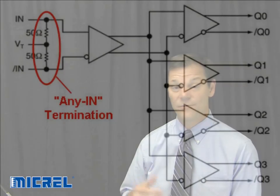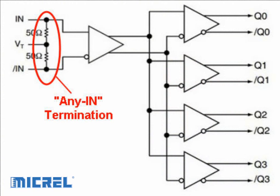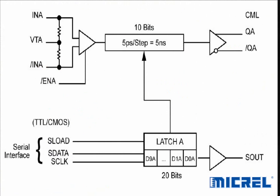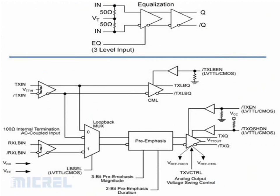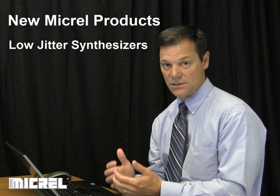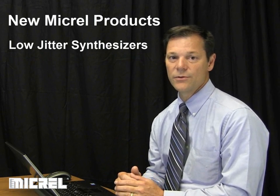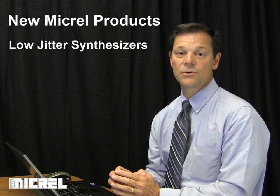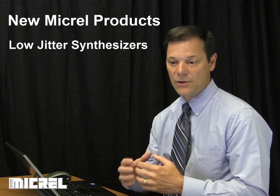The jitter is very low when you use the differential signaling, and Micrel offers the products as fan-out buffers, muxes and cross-point switches, dividers, delay lines, and even backplane drivers and buffers. But recently what we've added is now, instead of just making clock distribution type devices, we're making clock synthesizers. So today we're going to go over the several clock synthesizer parts that are now available from Micrel, and also go into the web tool and show you how to create your own part.